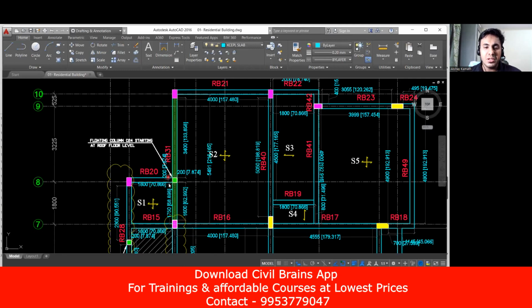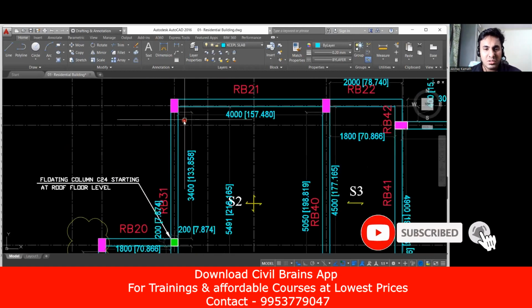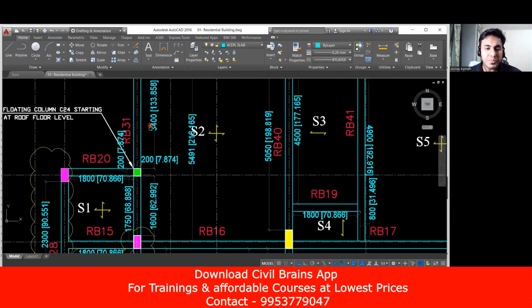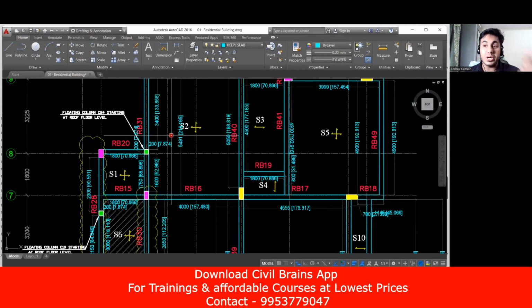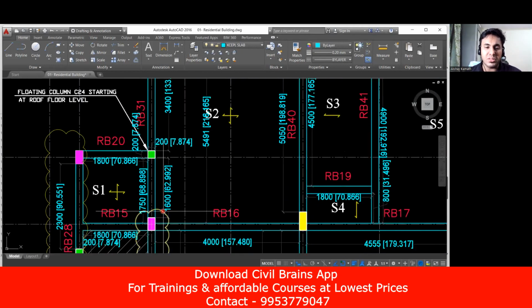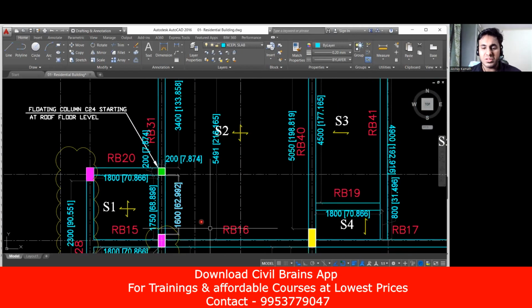But what has happened here is that there is a column coming in between, so I need to deduct the width of the column. Very simple. Either you take the complete length and deduct this part, or you take the measurement from column outer to column outer. This column outer to this column outer, I'm getting 3400. Then again this column outer to this column outer, 1600. While entering into the Excel sheet, I'll add this: 3.4 plus 1.6 will give me the total length of RB31.